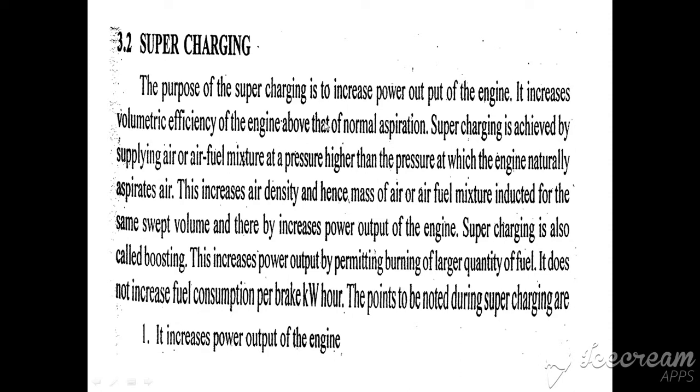It increases the volumetric efficiency of the engine above the normal aspiration. It supplies more air or more air fuel mixture than a naturally aspirated engine, and thus supercharging is also called boosting. This increases power output by permitting burning of larger quantities of fuel, and it does not increase the fuel consumption per brake kilowatt hour, meaning the specific fuel consumption does not increase. So this was the introduction to supercharging.